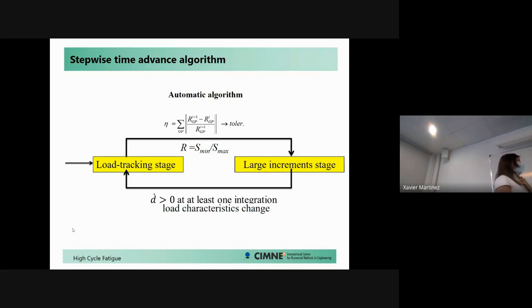Now, this might seem a little bit pesky for the user that unfortunately has the misfortune of setting up this fatigue simulation, but in fact it's all done automatically inside the finite element code. The user can customize this algorithm by setting up a specific step of number of cycles, 1,000 cycles, 50,000 cycles, it depends on the problem, that they want to use for the large-scale algorithm.